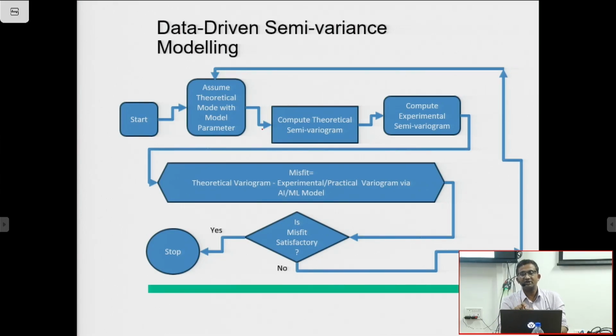Kriging means when your data is less, then the kriging based interpolation method may mislead the interpolation. You see, this problem is very prominent for those who are working in water resources projects. They have a small area where they want to collect data by deploying equipment or taking samples of the water chemistry. They have limited data. Sometimes in 3 years they could collect, say, 200 or 300 data points, because it also involves cost. They have to test it in the labs, different chemical properties, physical properties like that.